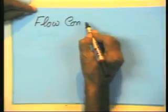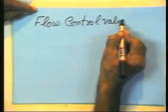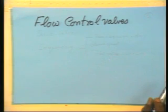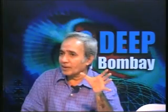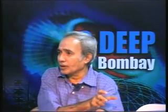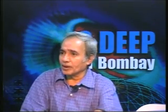Now, if you really want to have control on the flow, you have what are known as flow control valves. There are shapers and there are machines where a tool reciprocates driven by a hydraulic cylinder. You can set the flow control valve to a specific speed and then you can have it reciprocating up and down.